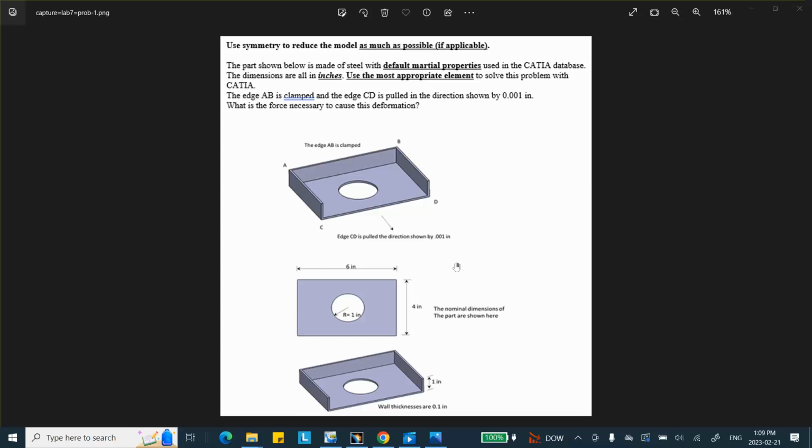By the way, to create this surface, because you're going to be using shell elements, you can do it based on creating a solid object, extracting surfaces and things like that, or create the surface directly. And that is how I'm going to do that, okay? So let me first create this base right there. And then I'm going to take these 3 edges and extrude it up so you create something like this, and then I'm going to cut it.